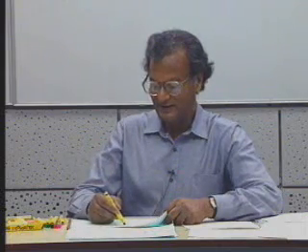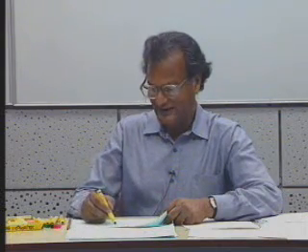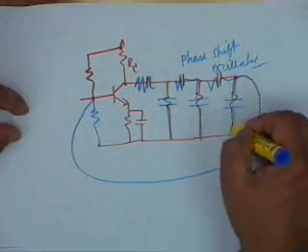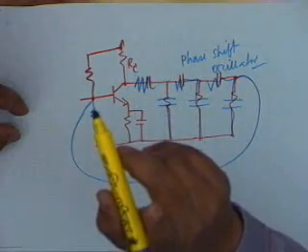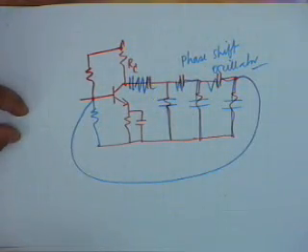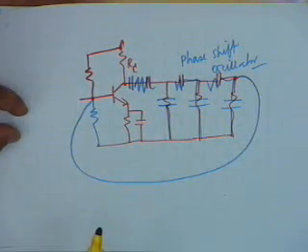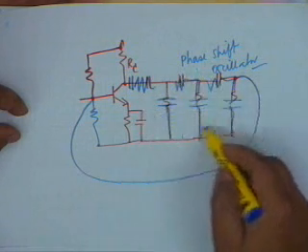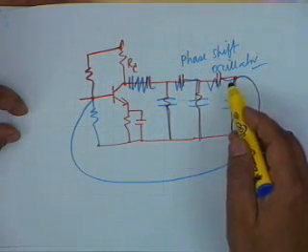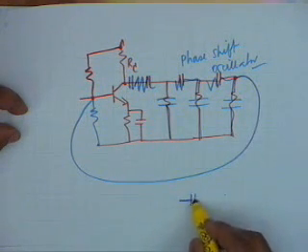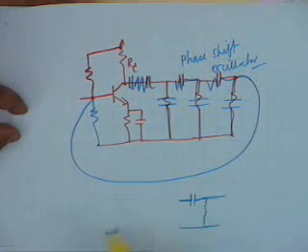We can do it that way also. If that satisfies Aditya, what we shall do is we will use an R here and a C here. It gives the same result, except that we require an extra capacitor here. Isn't that right? Because otherwise you cannot block out DC. That is why the CR circuit is preferred. This would be a lead circuit, pi, 180 degrees leading, isn't that right? Because in the CR circuit, the output is leading the input.